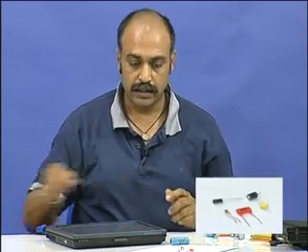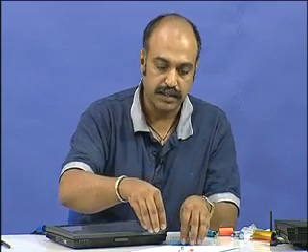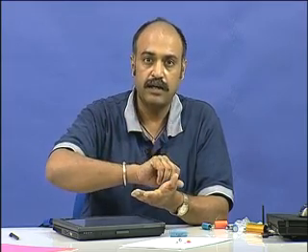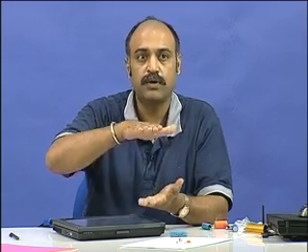Now, let us have a look at a few other capacitors that are bigger in size. Why should the capacitor be bigger in size? In the case of a resistor, we saw that as the amount of heat that it has to dissipate increases, the size also increases. But here the capacitors are not supposed to dissipate, but still you see that they come in various sizes, right from small to big. There are two things which are going to determine the size. One is the voltage. If you need to design a capacitor which is supposed to withstand a very high voltage, then you also need to have a dielectric in between which can withstand that field, which can withstand that voltage, and therefore the size grows up.